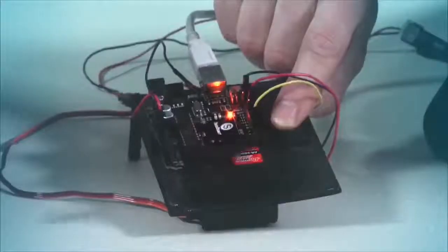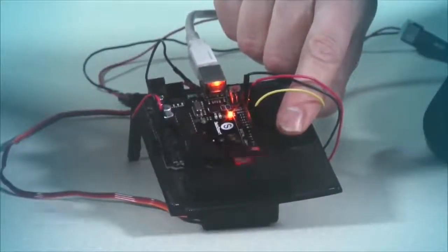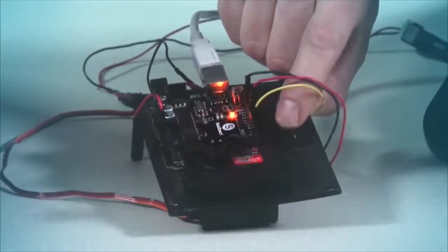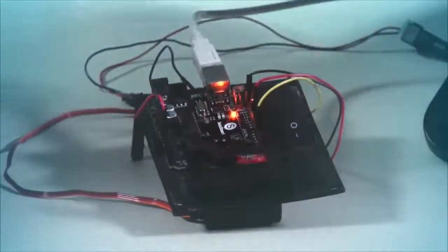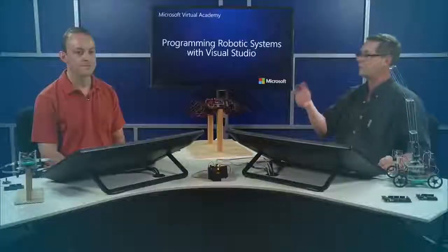Because the program's in a constant loop, it's going to constantly look for the value of that switch. The reason it's detecting that we made the change is because we're constantly reading the value in that loop function. So if we switch it back, it's still running. We'll just switch it a few times to show it wasn't a trick. It's running that way, and because it's in that loop, it's constantly detecting the value. And the loop is nice and quick. That's what you want, because you want the response to happen very quickly.